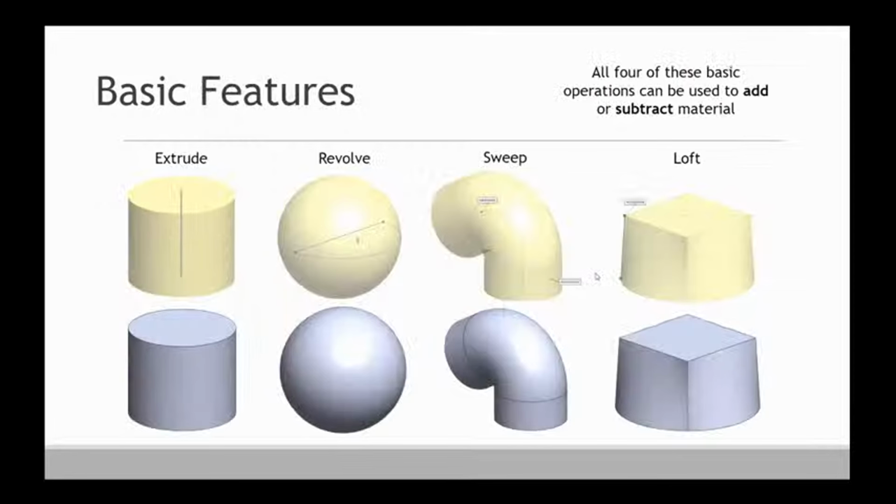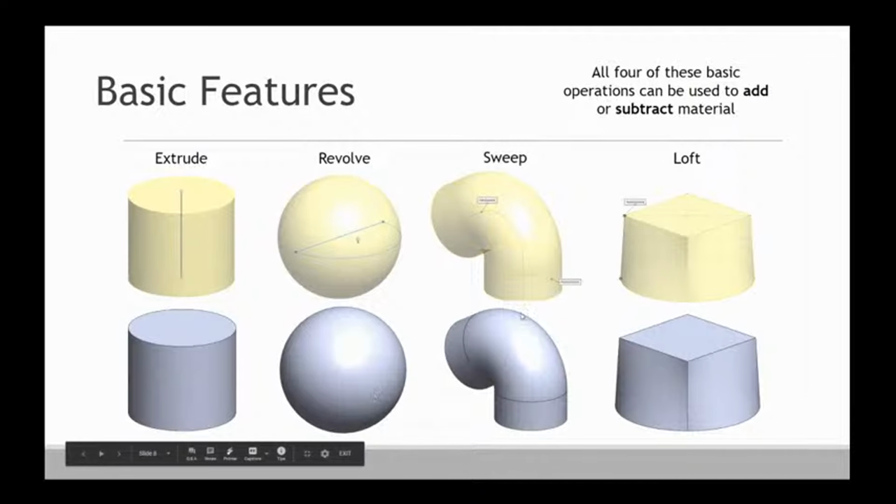To give you an idea of some of the different extrudes that we have, an extrusion is generally what we call creating a 3D object from a 2D sketch. For a regular prismatic extrusion, you just take a sketch and you can translate or project it up to a certain height, and that'll create your 3D solid. For a revolved extrude, you take a sketch and revolve it around an axis for up to 360 degrees of rotation to create a 3D object.